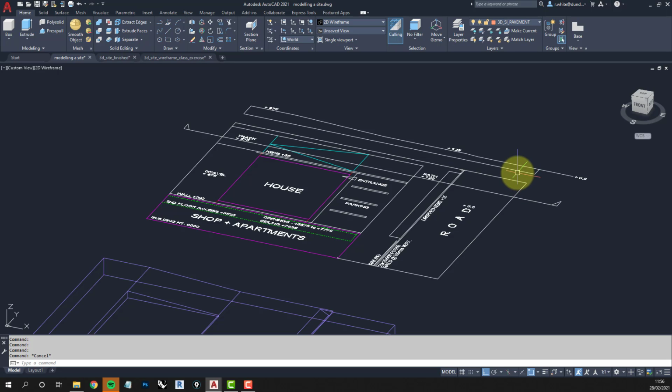Okay, let's just check what level the drawing is at, otherwise we could be compromised right from the start. So use the ID command: ID, enter, pick a point, and we're interested in what it's saying for the Z coordinate. So we're at Z of 0. Make sure you're at the world coordinate system when you do that, otherwise you're going to get a bogus reading.